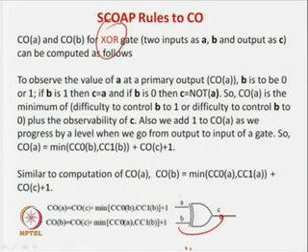Similarly, if A is 1, then you get B prime. If A is equal to 0, then you get B. Okay. So, both of them are okay for us. So, if A is easier to make 1, you apply that. If A is easier to get to 0, you do that. So, take the minimum of controllability of A to 0 and A to 1. Okay. So, whatever may be the case, you do that.